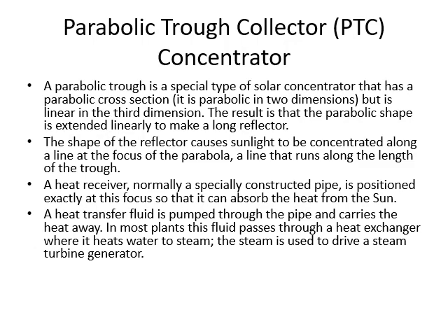A heat receiver, which is mostly called the absorber, is positioned exactly at this focus, right? And also the heat transfer fluid is pumped through the pipe and carries the heat away. Its temperature range may not be that extremely high like the other one we're going to see later, the tracking based concentrators, but this one is fairly enough, up to 400 degrees Celsius. And we can understand that although it's not directly relevant to the tracking, at least some degree of tracking should be there to capture the sun from morning and the afternoon.